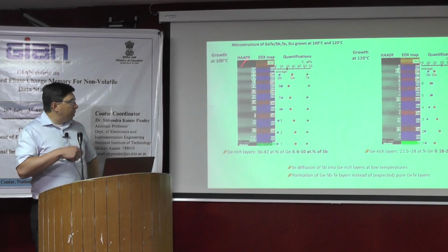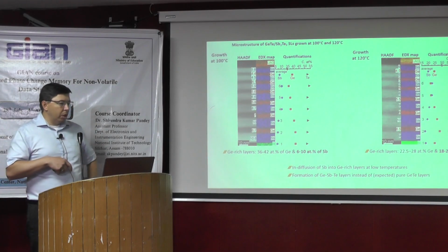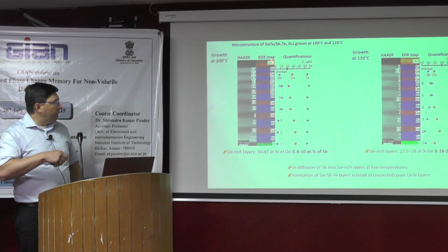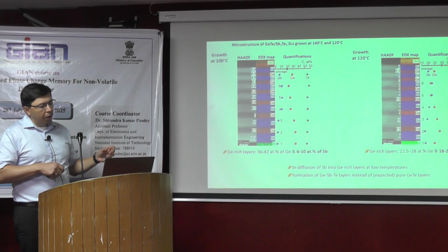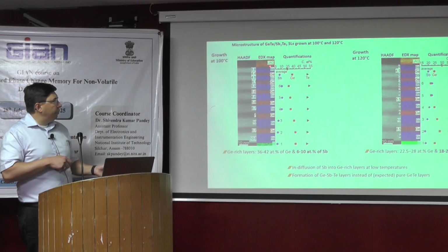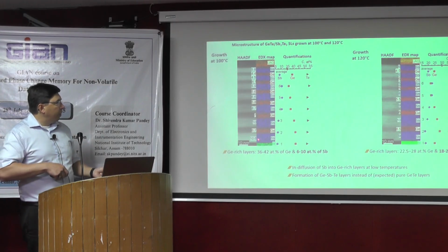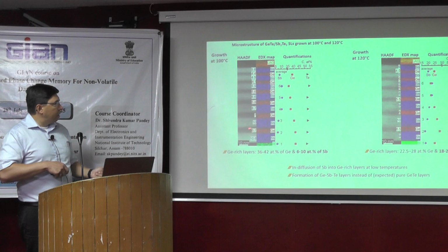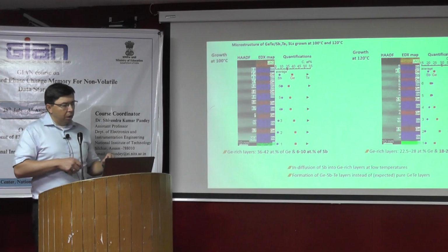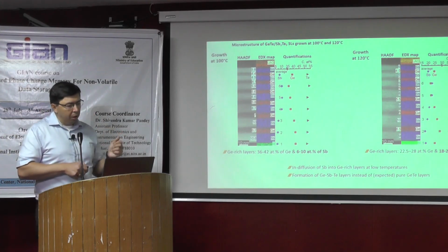This is our experimental result. We also reproduced such epitaxial superlattices. This is basic research. We did not aim to use very thin films. We just want to know the basic properties of this system. If we deposit thicker films, between 10 nanometers and 7 nanometers of germanium telluride and antimony telluride, we can also vary the thickness of such layers to see the effect of thickness on the local structure of these materials.